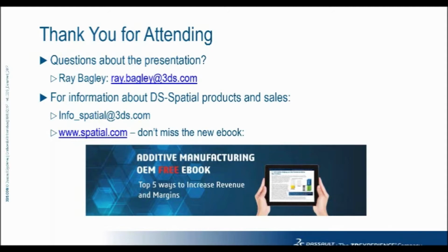And Ray, could you expand a little bit on how you manage slicing CAD and the STL files? Sure. Spatial has been known historically as a leader in providing precise modeling kernels like ACIS and CGM, and that gives us the power to do all kinds of geometric operations on precise CAD data. But we also have a more recently introduced technology called CGM Polyhedra, which is a modeling kernel written specifically to work with tessellated or polygonal data like we see coming in from STL data.